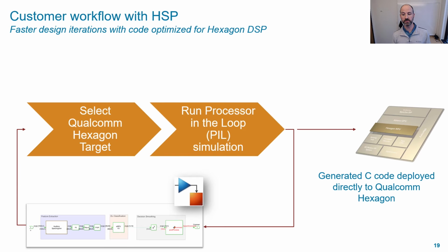By executing a PIL simulation, you're going to be able to gather valuable metrics about your application, such as the CPU utilization and numerical verification of the key signals in your algorithm. Now let's finally switch over to MATLAB and Simulink and do a more detailed demo.